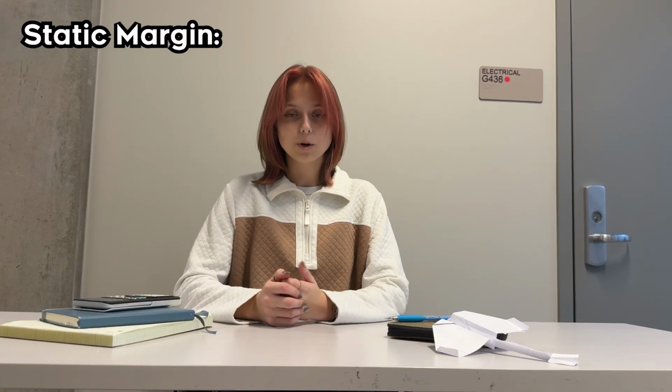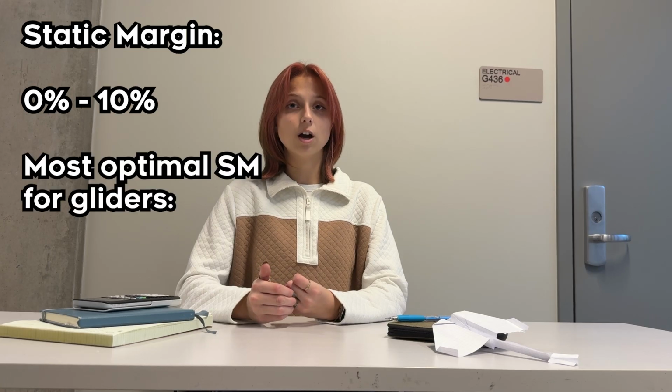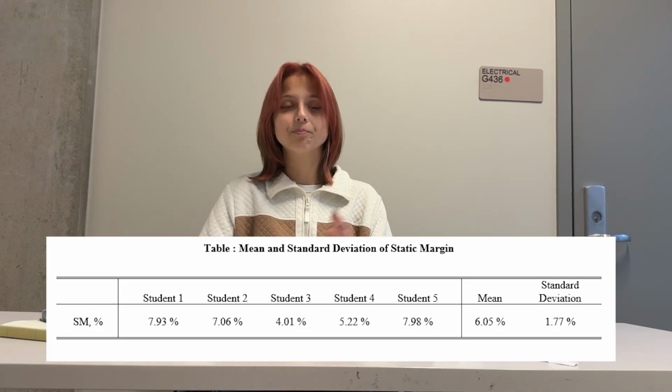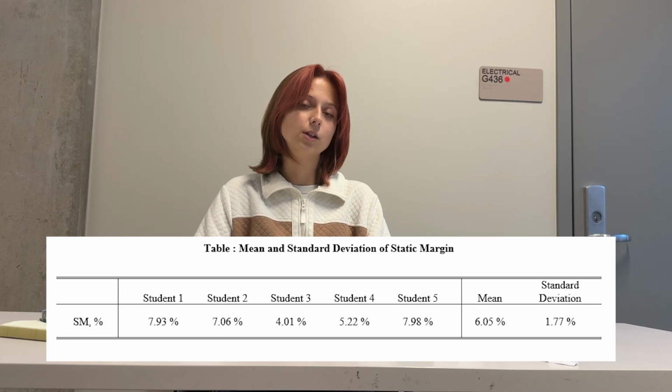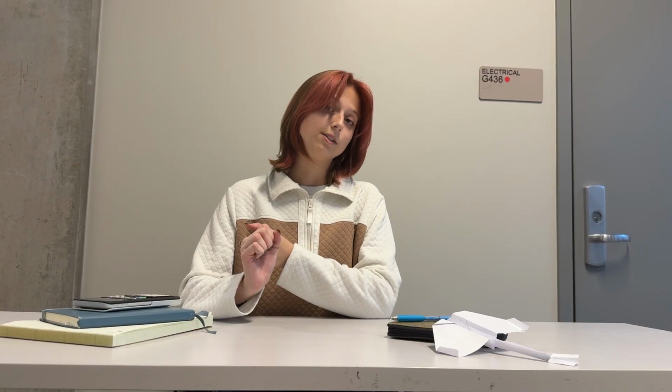Now, on top of this, you also care about the responsiveness of your system, which is given by the static margin. For gliders and small UAVs, a static margin between 0 and 10% while still being positive is optimal. For gliders, the most optimal is about 3 to 5%. And as per our data, everyone got a positive within reason static margin, roughly around 7 and 5%, averaging around 6%. From this, we know that our aircraft is both aerodynamically stable and responsive.